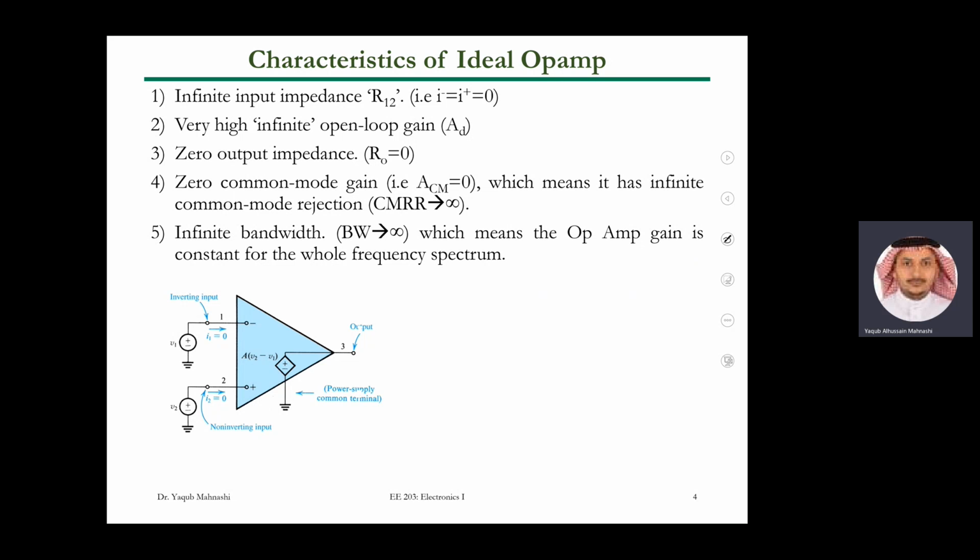Okay. So this is AD times V positive minus V negative, R out, R in. Right? All of this is inside your op amp. You don't see that, by the way. This is a model. And by the way, the op amp has maybe around 20 to 30 or even 50 transistors inside, but you don't see that. You can model that like a behavioral model. So the ideal one will say that this is infinite. It's not there, right? And this is the case. This is infinite. And the result of that is that the entering currents are zero.